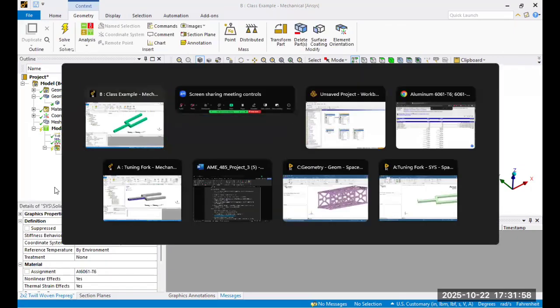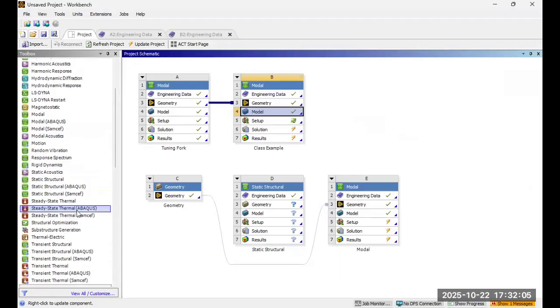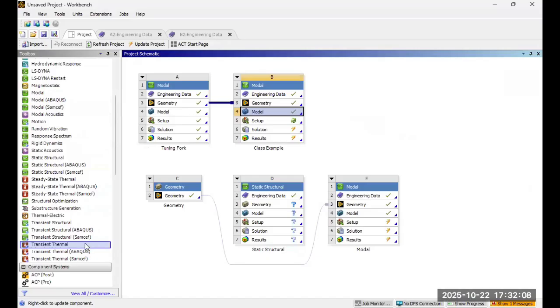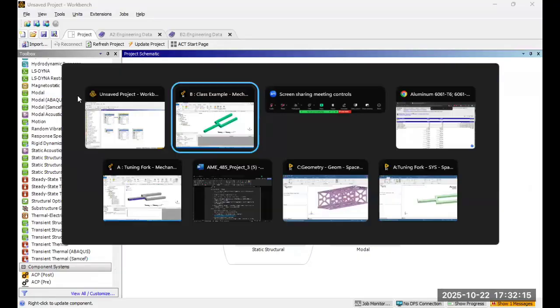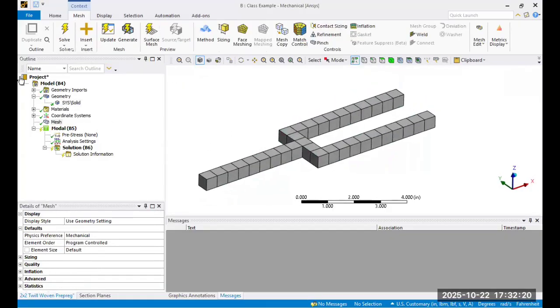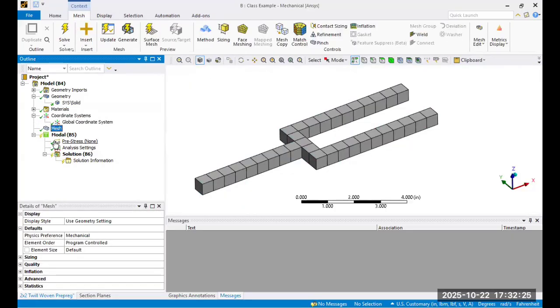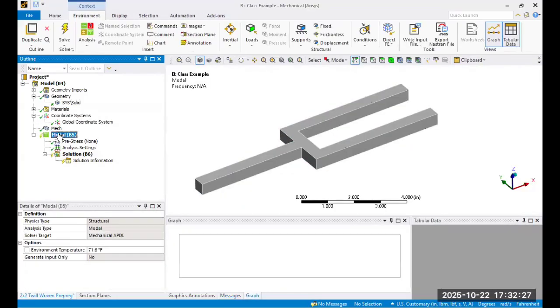And also critically, when I was in the static structural module, I went and dragged in a modal analysis. So we did static structural. Your homework is a transient thermal, and that's what we did last lecture. Now we're doing modal. So hopefully, this is being useful to help you guys build up the toolkit for stuff you might see in industry. So this is all just default mesh. I defined my material property and this default mesh. Okay, and now I'm going to run a modal.